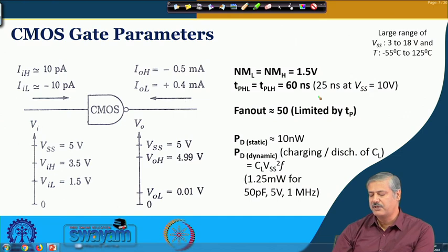This is another important characteristic, and dynamic power consumption is one important consideration here, which is one path is there that half CV square, right, during charging, and during discharging the similar power consumption is there, okay, the same half CV square. So, together it is CV square that you can see, and as many times it is getting charged and discharged in one cycle given by the frequency of operation, right.